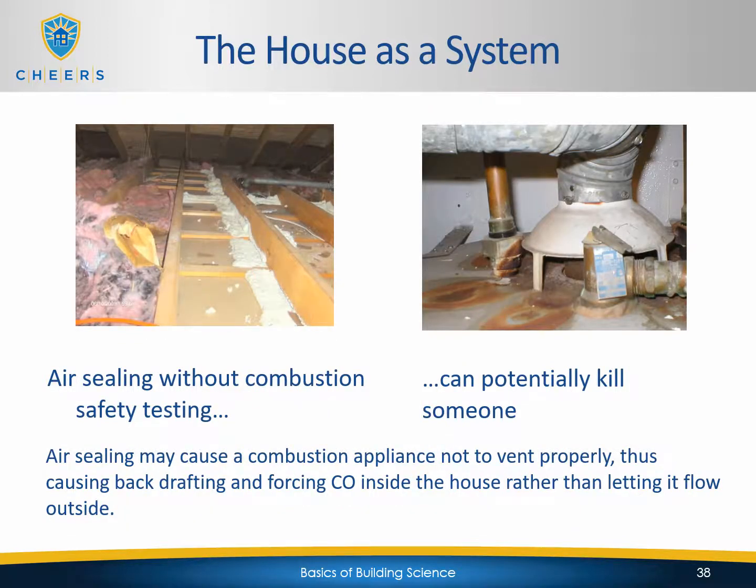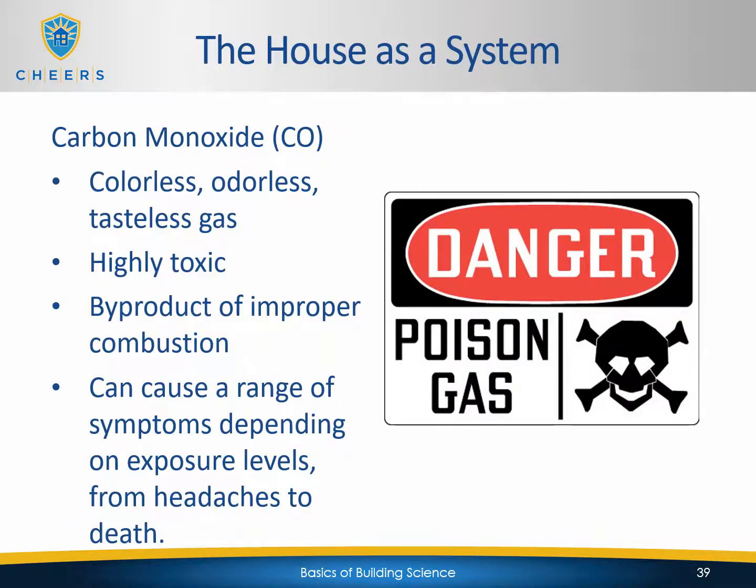Air sealing without combustion safety testing can potentially kill somebody. Like I mentioned earlier, air sealing may cause combustion appliances not to vent properly, thus causing backdrafting and forcing CO inside the house rather than letting it flow outside. CO is a very dangerous chemical and it can kill somebody.